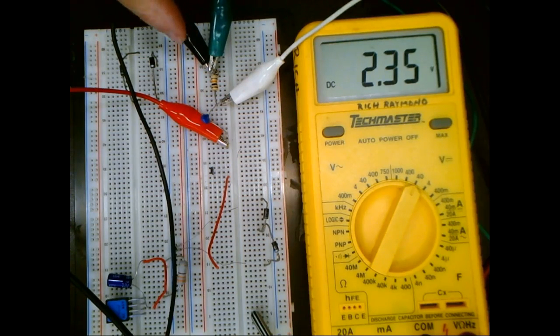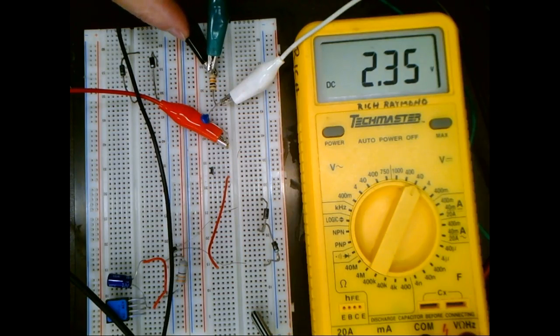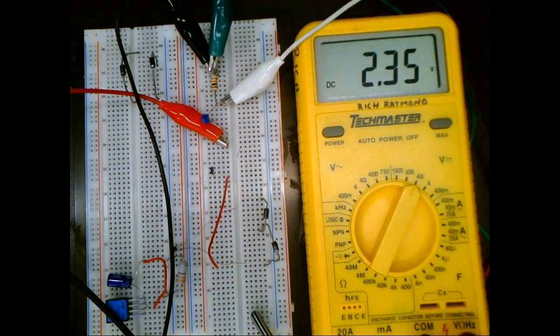Yeah, the resistor's on the bottom. Here's my common. Okay. So this means if I was to swap it around, just by swapping my power supply around, then the voltage would go down. So if we put the resistor on the top, and my thermistor on the bottom, and it's a negative temperature coefficient, then my voltage would do what?